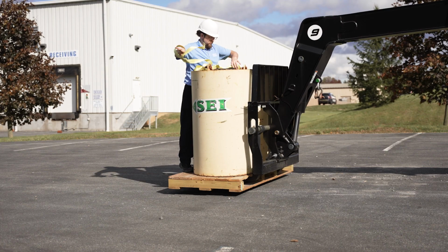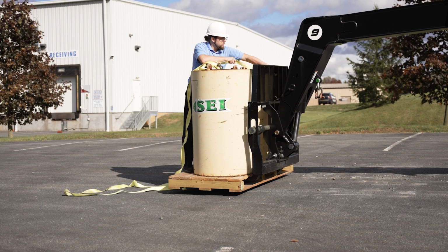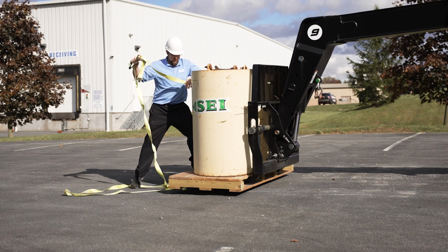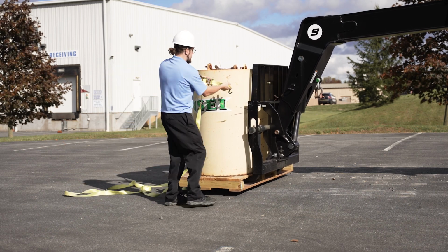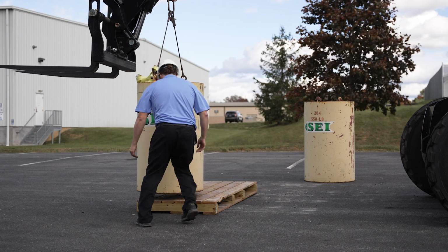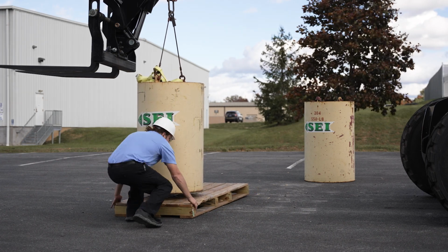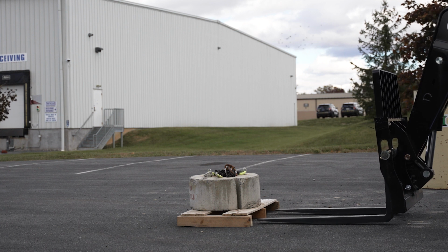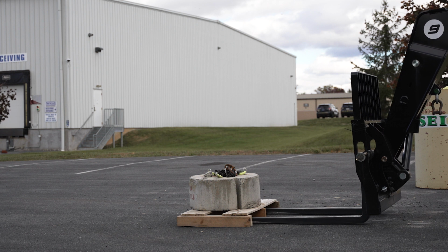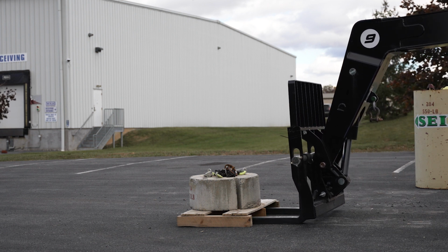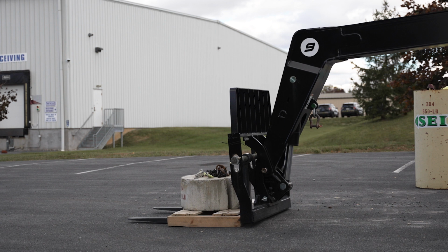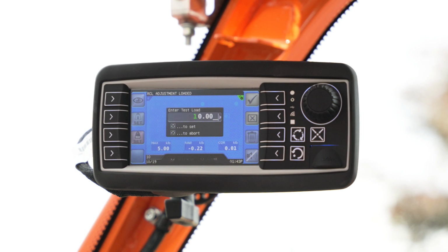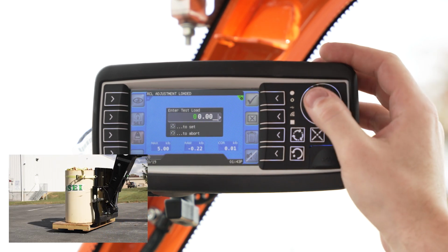The first load needs to be within 70% of the machine's maximum capacity when fully retracted without exceeding it, which is usually the highest load available on your load chart. The second load needs to be near the middle of the machine's maximum capacity. The third load needs to be near maximum capacity of the machine when fully extended, which is usually the lowest load available on your load chart. It is the operator's responsibility to ensure that they do not overload the machine by attempting to use an incorrect weight. Pick the first load and press the Max Set key for the weighted load adjustments.